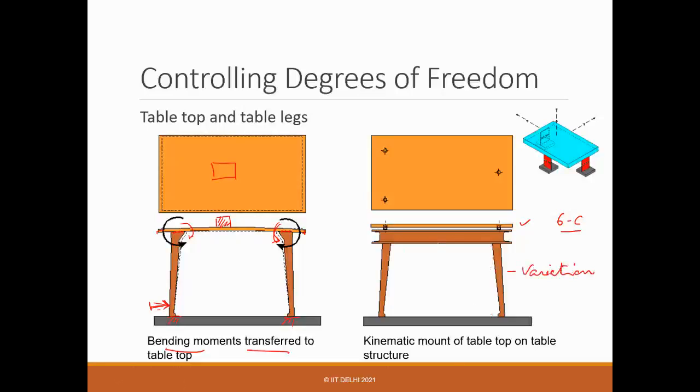You can make the bottom part heavy, but the top, where you want to put your sensitive equipment or anything you want to mount, you don't want it to be affected because of this variation on the floor, right? So what you do is you use a kinematic mount. So this piece is called a kinematic mount. So 3 of them.